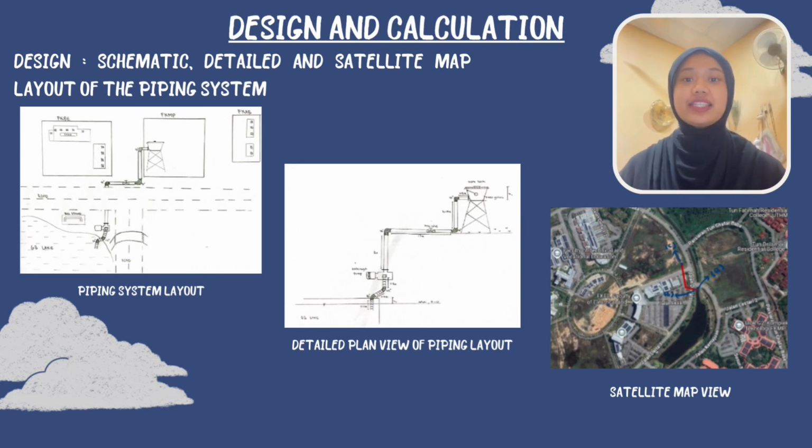Not only that, this proposed pipeline structure can be verified using a satellite map view, providing a realistic interpretation of the schematics. This imagery helps bridge the gap between schematic planning and execution, ensuring the pipeline route works well with existing infrastructure. The satellite image also aids in making decisions about safety zoning, pipe trenching, and pump placement. It also aids in estimating elevation profiles and horizontal distances. This satellite reference strengthens the proposal's credibility.